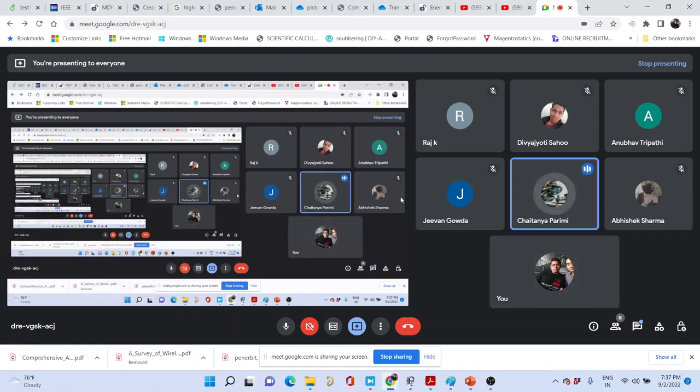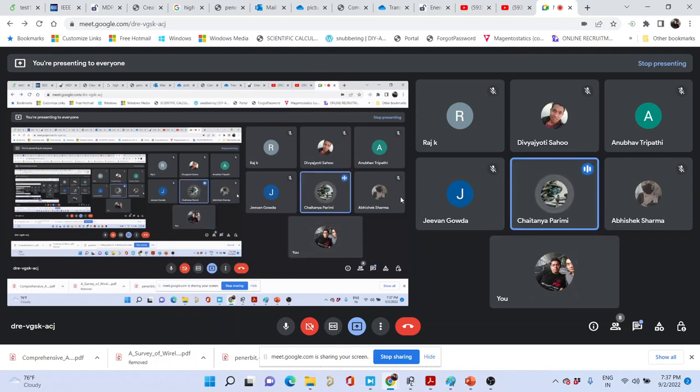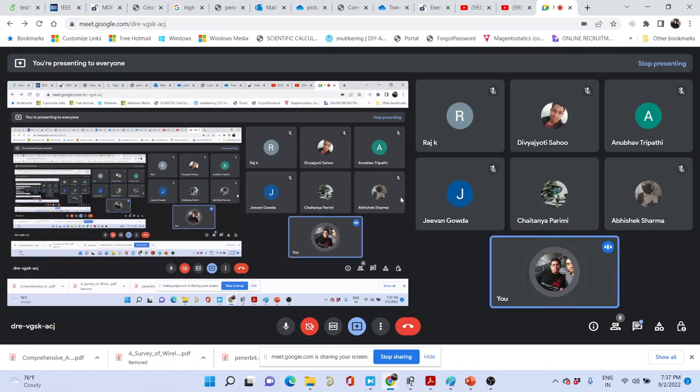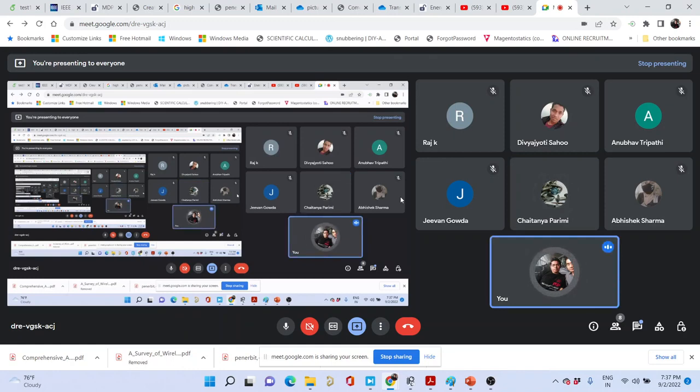We'll be getting zero steady state error for step input, and that's unity gain. The choice of unity gain will be coming when all the closed loops will consider 0. I couldn't understand. I'm talking about the disadvantage of the PI controller. Disadvantages or advantages? Disadvantage. I have told you that for tracking a DC signal, a PI controller is a very good option because the gain at omega equal to 0 is infinity. As the gain is high, yt becomes equal to xt, so you get a steady state error equal to 0.